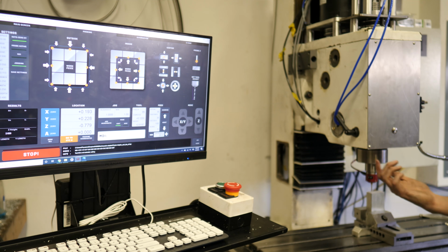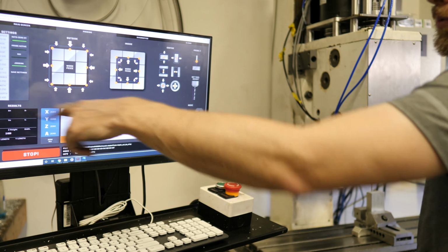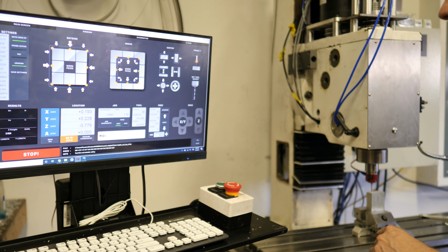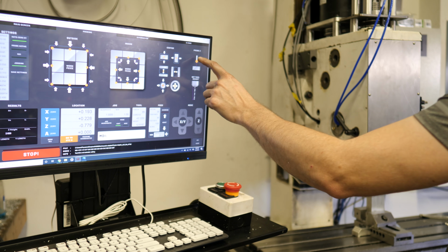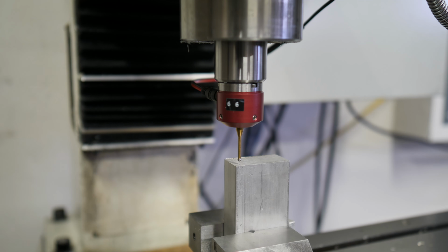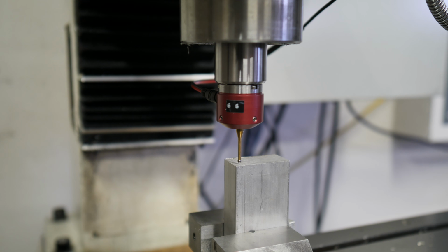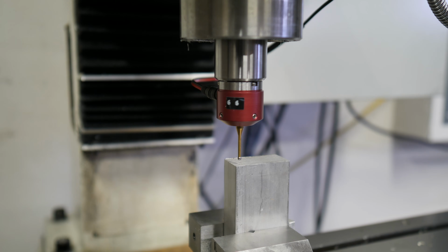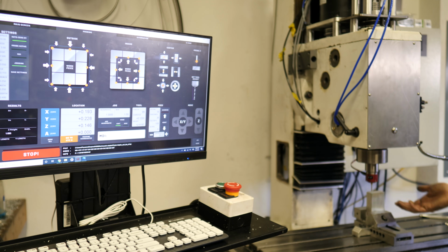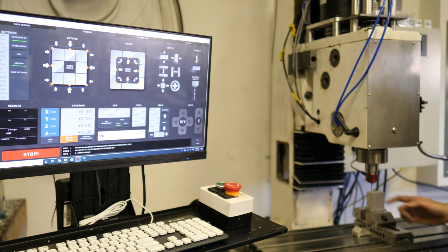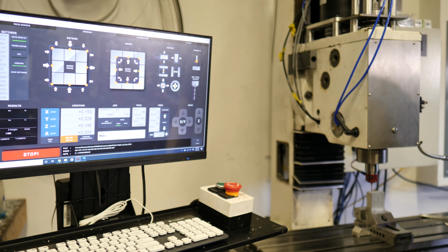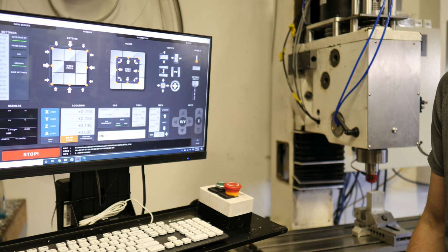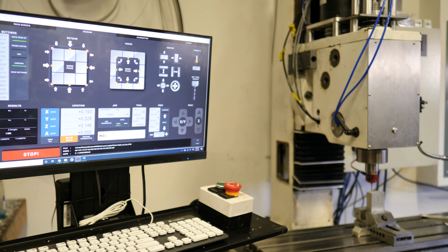It's above the part. You just have to be somewhere above the part. It will give up after its search depth, which is 0.4 inches at the moment. Click the tool, the probe Z. It's going to go down. It's going to measure it. It's going to measure it again at a slower speed. And it'll even go back to where you set it initially, which is pretty handy. And there you go. You've got your full datum set to the very corner of this part. By the way, both of those buttons that you need to do that are on the main screen as well. That's why I put them there, because that's how I set up most of my workpiece datums.